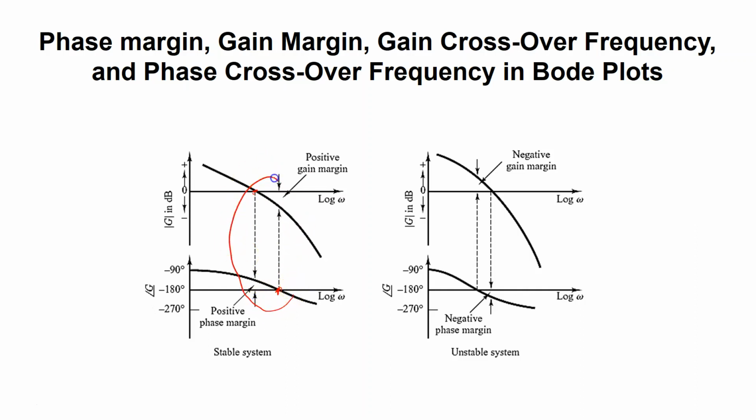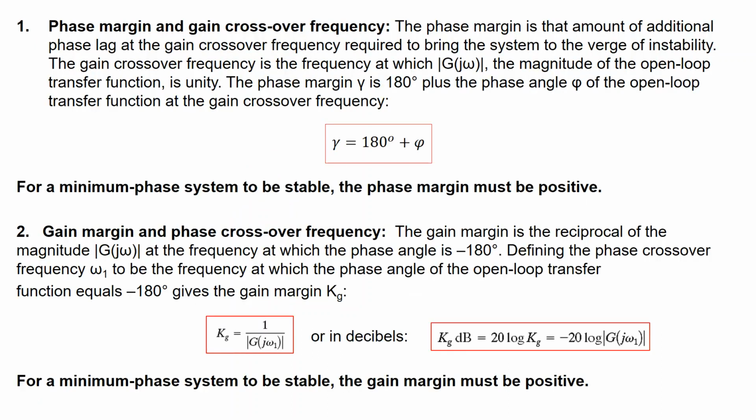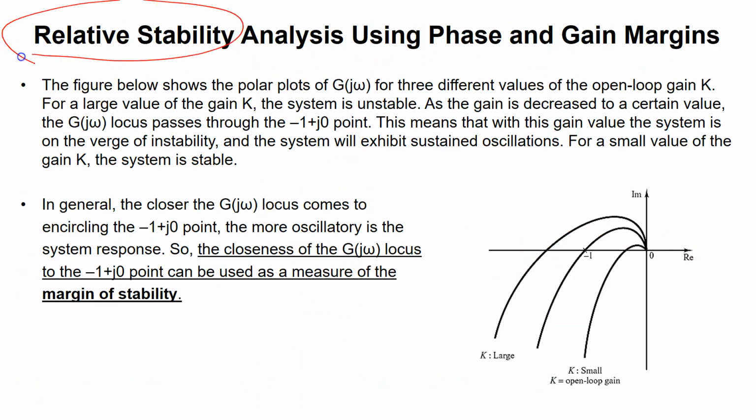And in the mid-range, we know this phase and gain margin, they are indicators of what? Of a relative stability. So every portion of these frequencies would tell us something, right? From complexity to relative stability to steady state error. You probably see that nowhere is exactly telling me anything about transient response. And yes, that's correct. That's what the frequency response is. It's not directly talking about transient response.